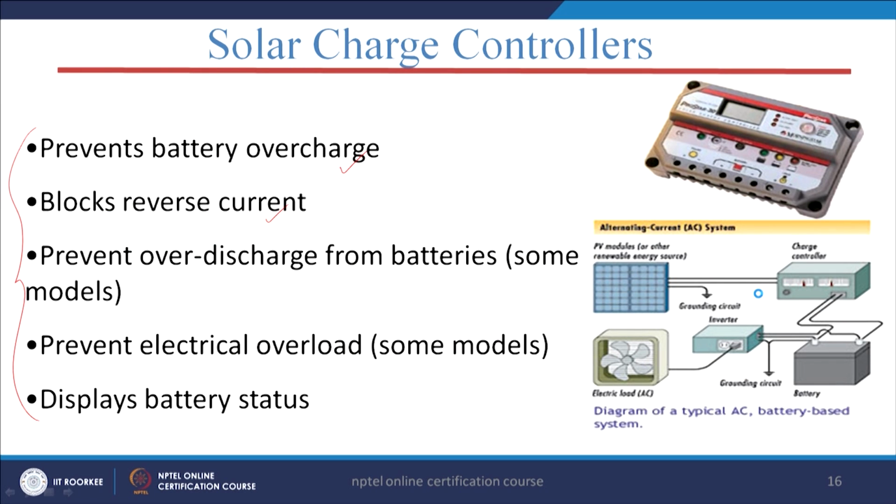So, that particular charge controller helps in blocking this reverse current, and also prevents over discharge from the batteries in some cases, and also prevents electrical overload and displays battery status. So, these are some of the key functions of the charge controller, which is used basically here.